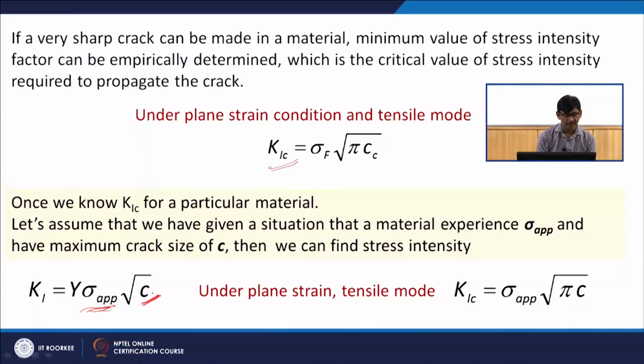So, knowing the applied stress from your design, and finding the crack length from some NDT evaluation, and using whatever geometry we are using, if we are in plane strain condition under tensile mode, then Y will be under root pi. I can calculate the stress intensity factor under mode 1.